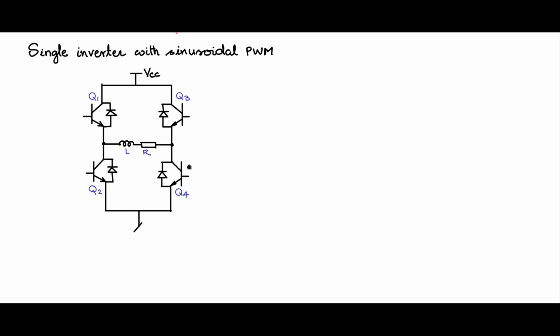Depending upon the way you modulate it, this full bridge converter could provide a DC-DC converter if you put a transformer with center tap secondary. In this case, you are putting an LR load, and the voltage across the center points of the bridge will be an AC voltage. Now we want to get a special quality of AC voltage: one with a fundamental of 50 Hz sinusoidal, so that when you filter it out, you get back your fundamental sinusoidal wave shape.